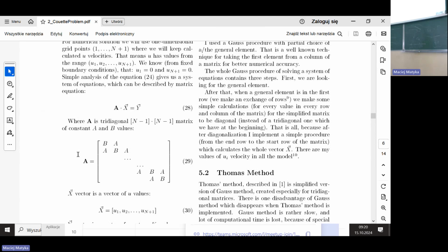Yes, but from the symmetry of the system, there is no mass transfer in the y direction, and then the pressure here will not accelerate the flow. So from the symmetry, the flow will be only in x direction, and there is no gradient of the velocity in x direction.